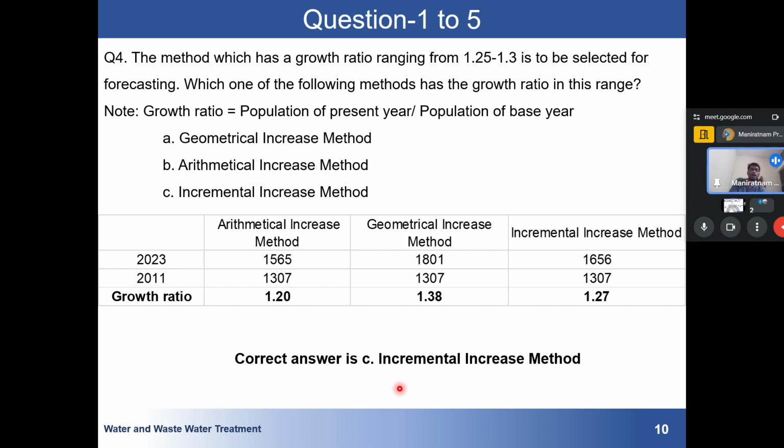Remember, they are asking just a simple question, but when you will be designing your water treatment in a real case, you will be facing this as your first step. These are three basic methods. I will be explaining one more method, that is logarithmic increase in population. People are using logarithmic, as it has been seen that none of these methods is applicable in a real world scenario.